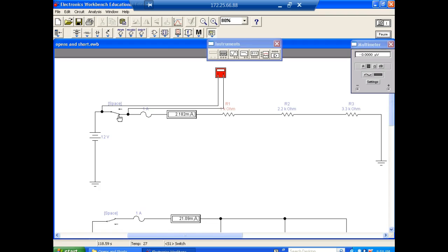So right now, if I went back to these outlets, these switches back here, and I measured across the switch that's controlling these lights right here, what would it measure? It's going to measure 0. What would this switch measure? 120 volts, or whatever we have.